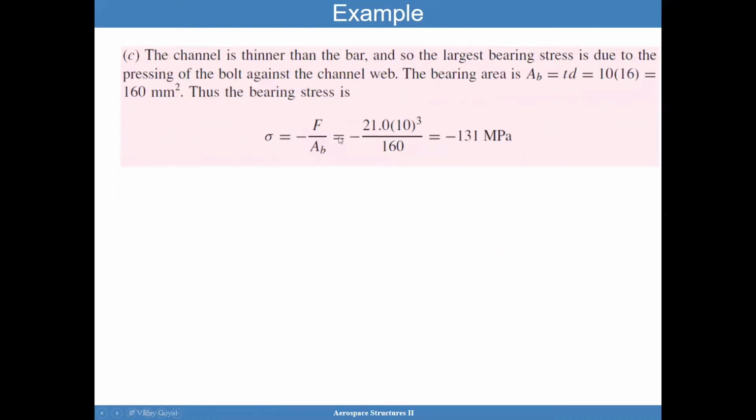You can also look at the bearing stress due to this bolt acting on this part. Since the bearing area equals T times D, the thickness being 10 and the diameter being 16, you can calculate the bearing stress as 131 megapascals.